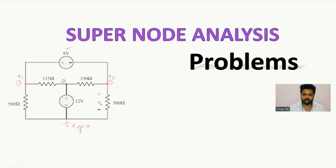How will we write it? With respect to 1, V1 minus V3, apply KVL in this direction. So V1 minus V3, and the second polarity we write is minus 8, that equals 0. So V1 minus V3 equals 8.